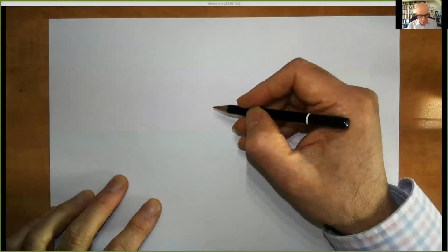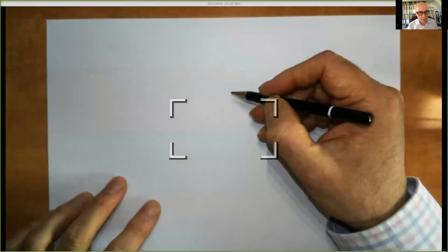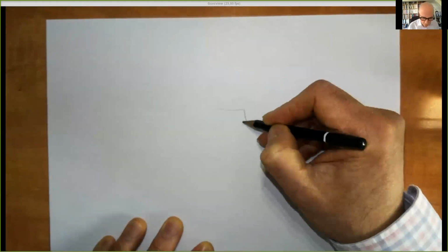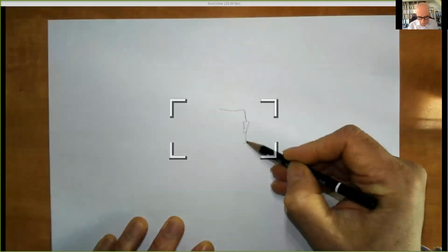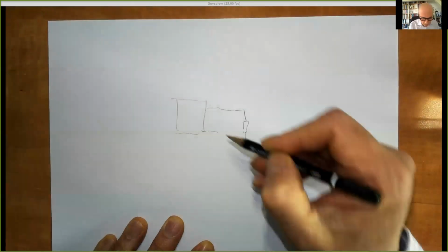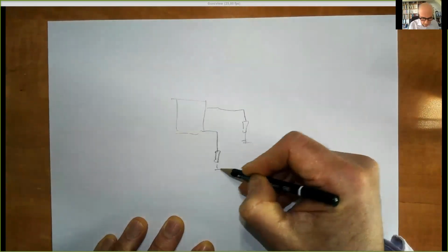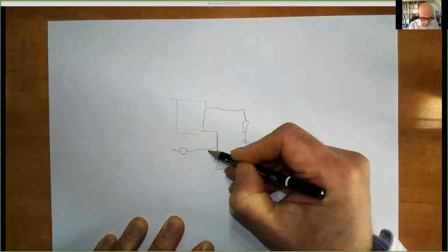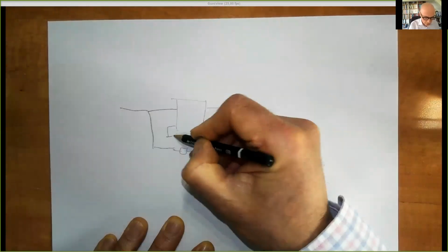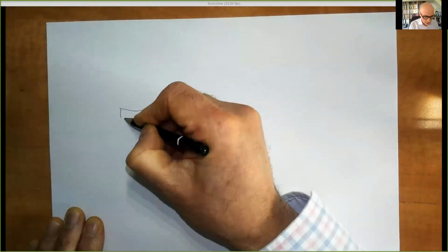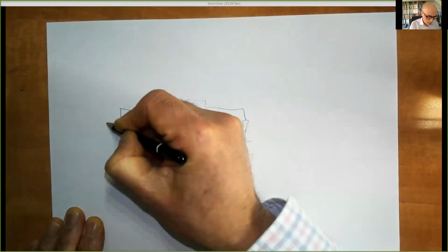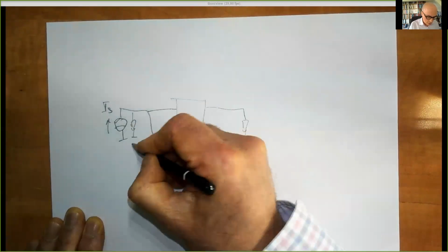Okay, so let's make a current amplifier with negative feedback and passive feedback. So we have a load. We want to sense the current. The load is grounded, so if I have my controller here, I will sense the current in the opposite terminal. Make a current divider. Then a part of the current will be flowing here and subtracted from the source. So that is how I design a current amplifier. So here is the source, IS, and the source impedance.